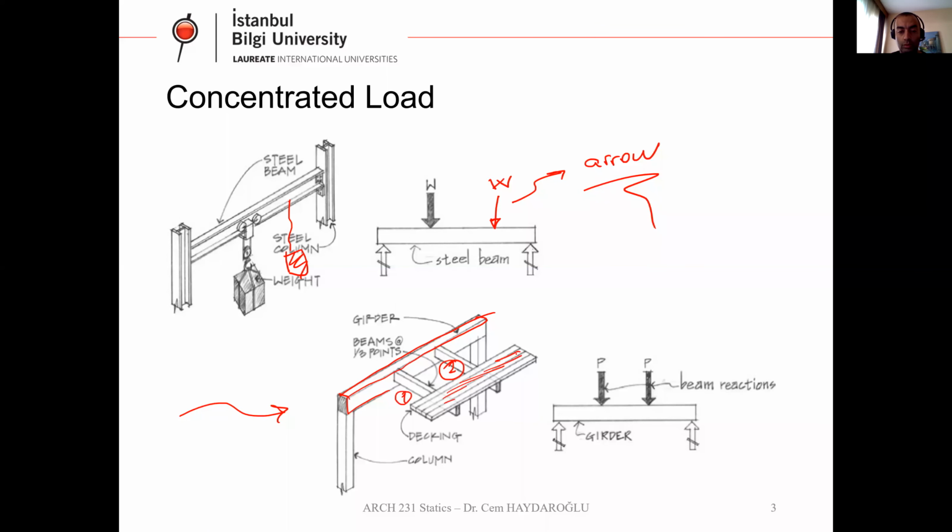Live loads, people or furniture or other things, stay on top of this floor covering. So the floor covering takes all the load and transfers it to these two floor beams, and these two floor beams transfer the loads to the main girder, to this point and this point.